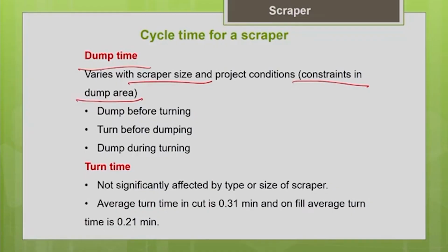That is why very commonly you can see that if the terrain is very hard, like very tough consolidated clay, in order to enhance the productivity of the scraper, they initially use a bulldozer with a ripper and rip the soil. They loosen the earth so that you can easily use a scraper for the loading operation. That way you help the scraper to reduce the loading time.